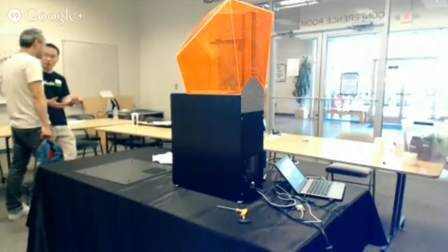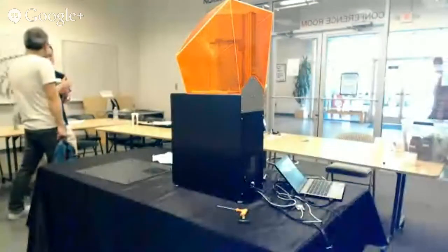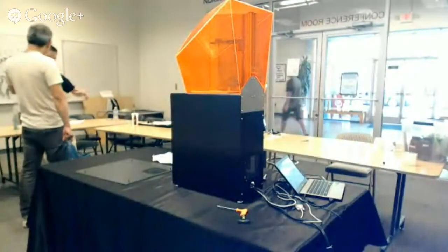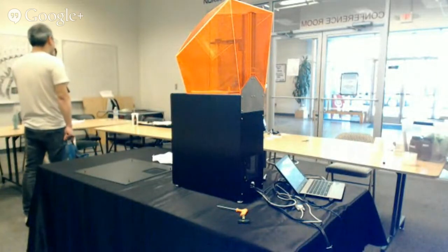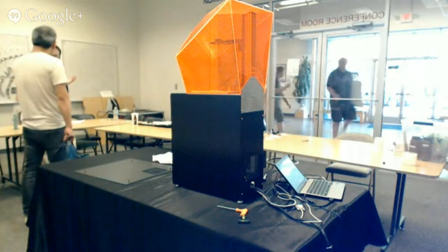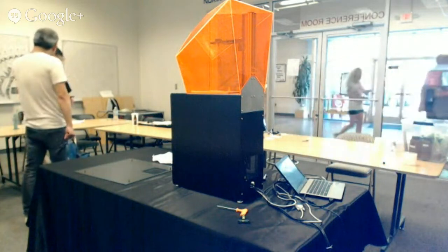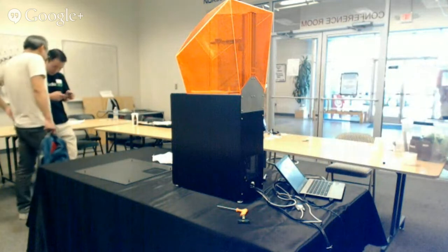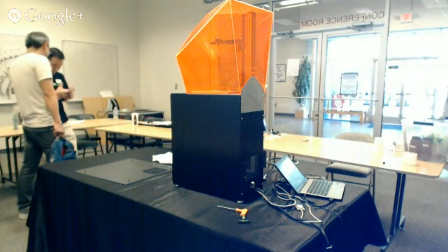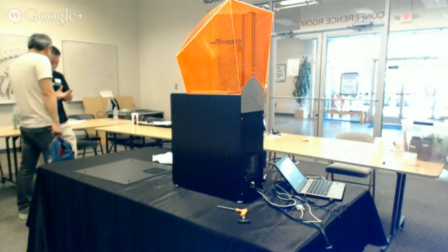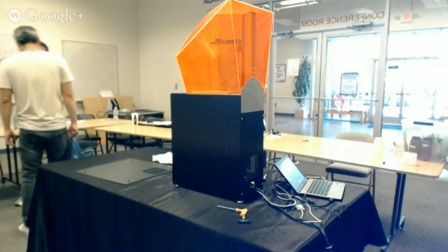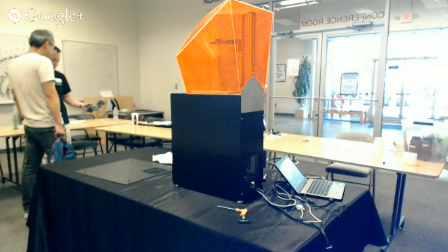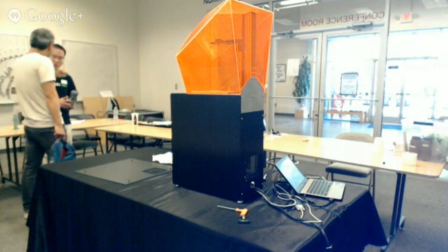Could you explain to me then what the layers of the build vat are? Because I thought this is just a... I'll tell you the ones that I know of, but Ted has said that there's a secret blend of 11 layers in here. I don't know what they are. From a user perspective, there's the acrylic floor, then there's a layer of silicone, and there's the film on top. Got it. When you look at the film, it clearly has multiple layers in it. You can see between there and there. So this is actually not just one film. This film itself has a couple of layers. The silicone, to my knowledge, doesn't have anything underneath it from the vats that I'm using.